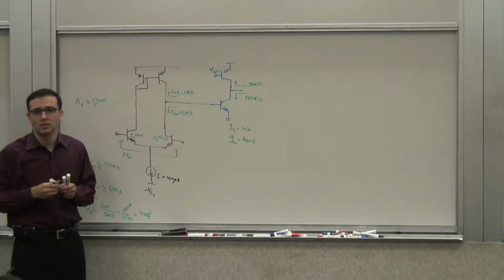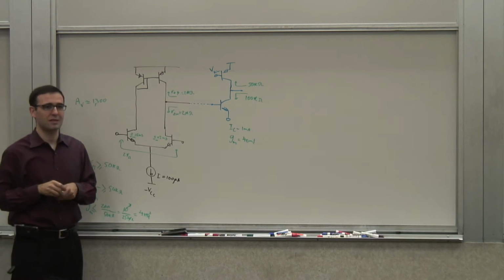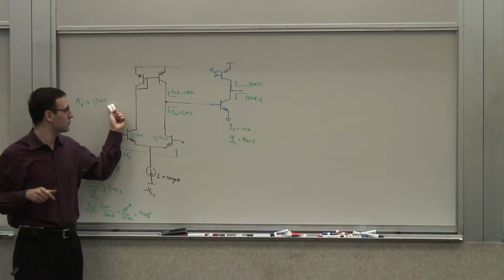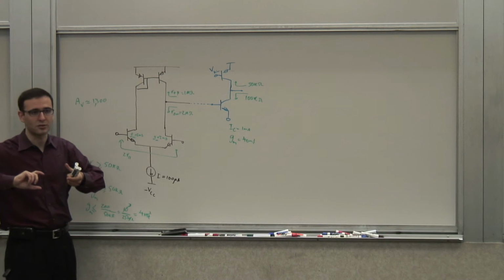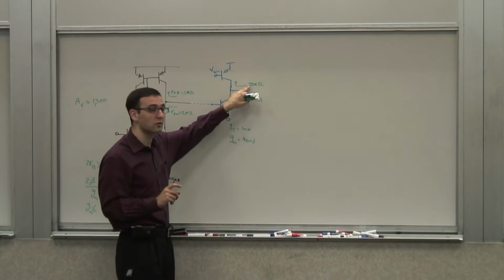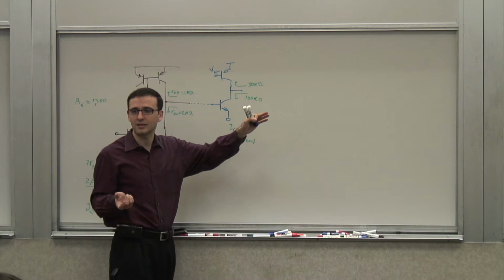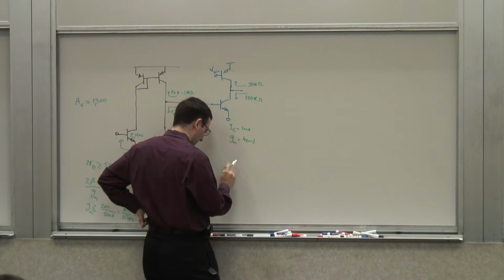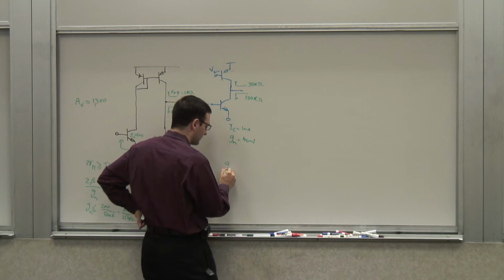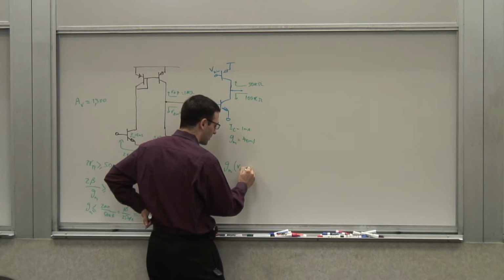Right? So it's the parallel combination of those 2, and it shouldn't be too surprising to you that it will come out to be the same number, right? Because they have the opposite dependence on the IC. So basically, this product of GM, RON, and ROP is independent of IC. We did that before, right? Because if you think, just to refresh your memory, the gain is GM times RON in parallel with ROP.